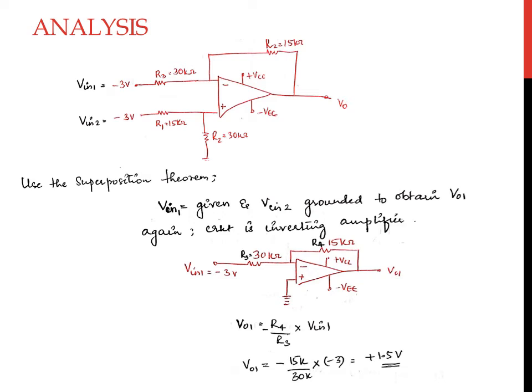In order to analyze the differential amplifier circuit, we need to use the superposition theorem. The superposition theorem states that a circuit can be analyzed with only one source of power at a time. The corresponding component voltages and currents are algebraically added to find out what they will do with all the power sources in effect.